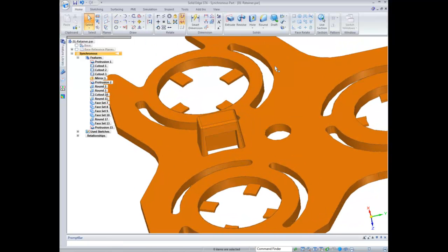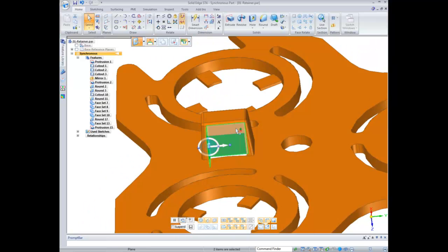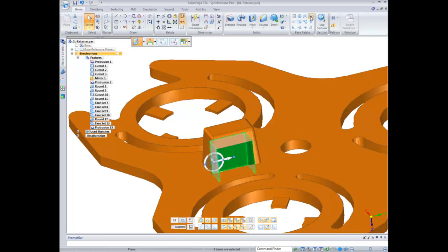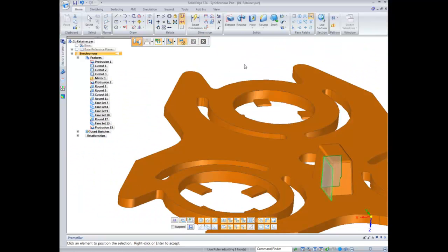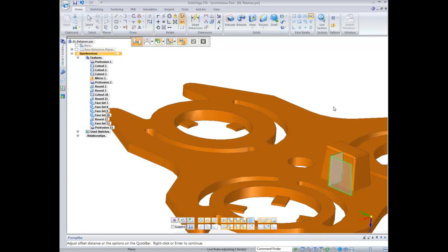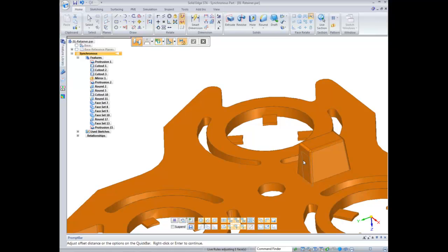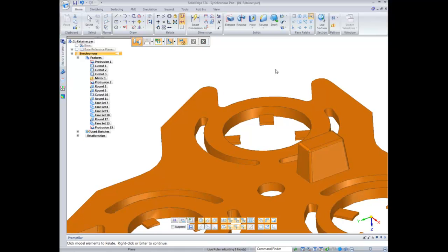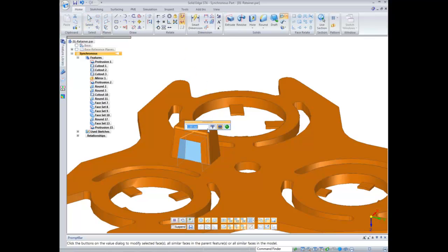Another way, you can also select the faces first before using offset. So let's say we want to select these 3 faces. We'll pick those first, we'll hit offset, and then we'll select the face that we want to offset to in order. So we selected the left one first, so we'll select that one, offset it. I want to offset to this back face, 1 millimeter, and the left side as well. So now if we go back in, we can click the edit handle here, and we have these options here.